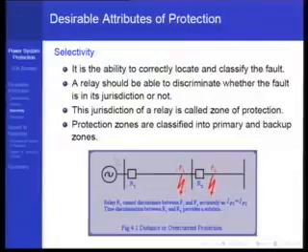So in that sense the jurisdiction of the line is up to this bus, and the jurisdiction of this relay is up to this bus. Here I am expecting that there may be a separate bus fault detector. If it is not, then the jurisdiction of the relay is also the bus as well as the corresponding line. So this jurisdiction is also called the zone of protection.